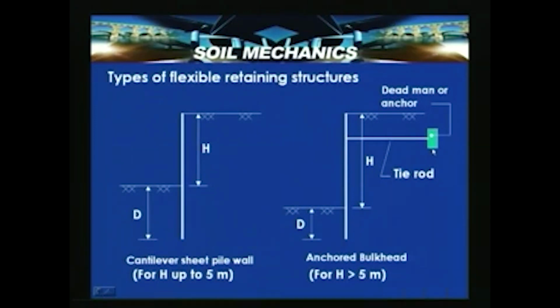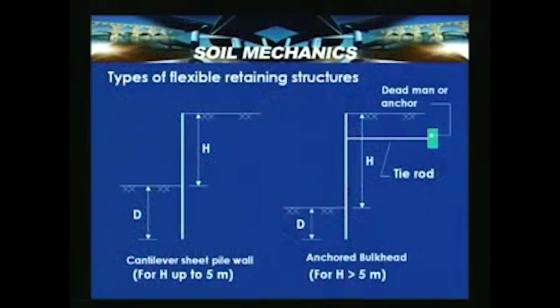The wall derives its support from the net earth pressure resistance. When it moves this side, it is possible that there is an active case here and a passive case here. That net pressure serves as the anchorage capacity in this case.